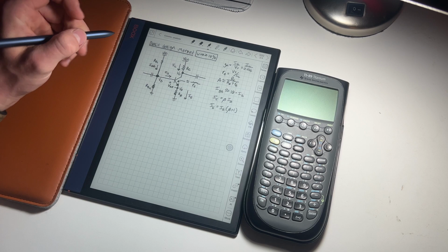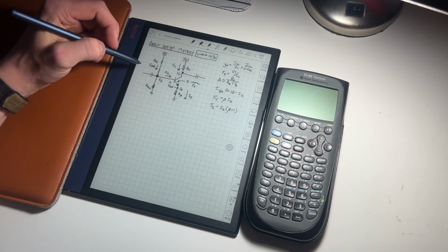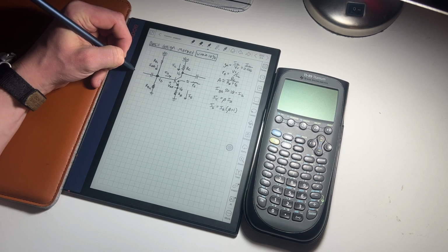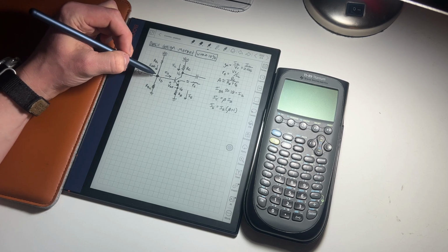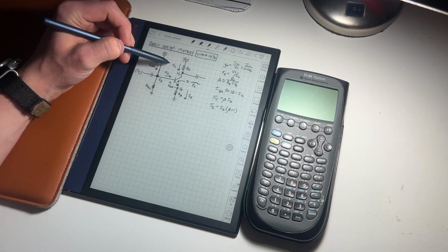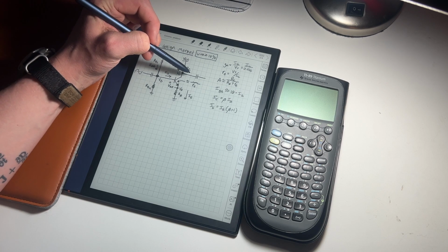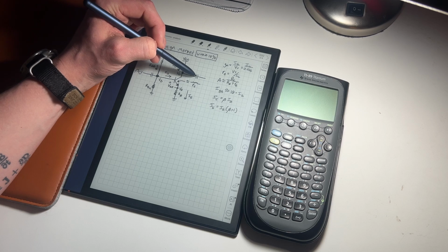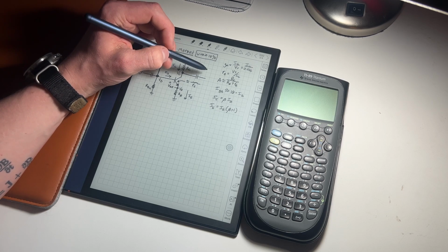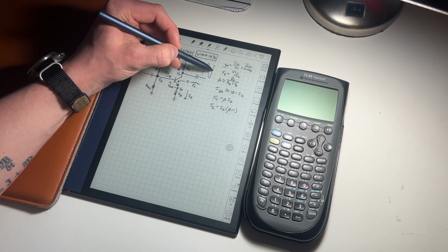And these 2 capacitors are what's known as AC coupling capacitors. What this allows you to do is input an AC waveform here whose center is at 0 volts, amplify it, and have it ride on top of a DC signal in here. And once you amplify it, it comes out here on a DC signal, but only AC can pass through this capacitor. So on the output, you'll have a much larger signal still centered around 0 volts.